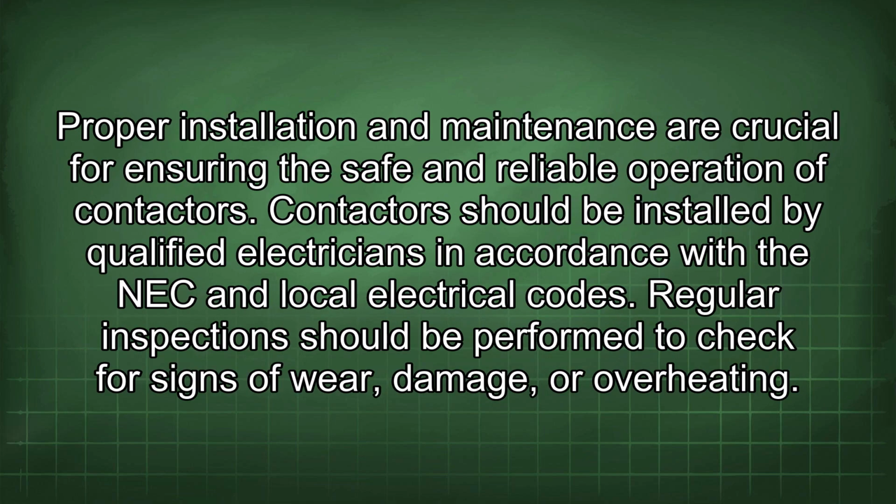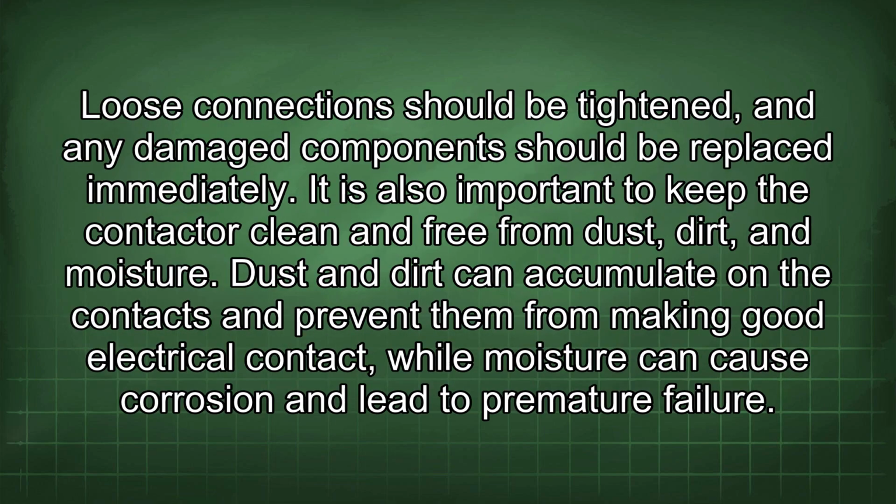Proper installation and maintenance are crucial for ensuring the safe and reliable operation of contactors. Contactors should be installed by qualified electricians in accordance with the NEC and local electrical codes. Regular inspections should be performed to check for signs of wear, damage, or overheating. Loose connections should be tightened, and any damaged components should be replaced immediately.